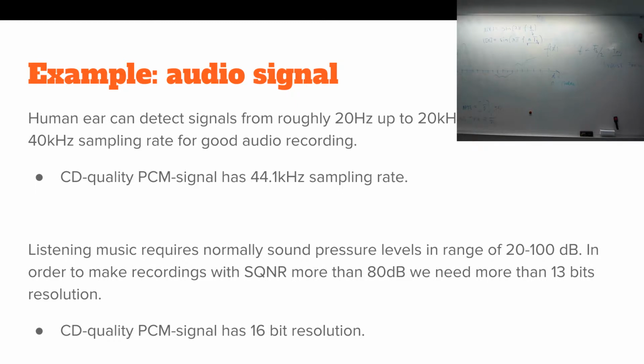Basically, you want that electronics to be flat here, so 0 dB, and then it can have a simple high pass filter in the beginning, and also you can start cutting off the higher frequencies after 20 kilohertz, which is good since your Nyquist frequency is somewhere here, and you want to basically attenuate this part of the signal out.